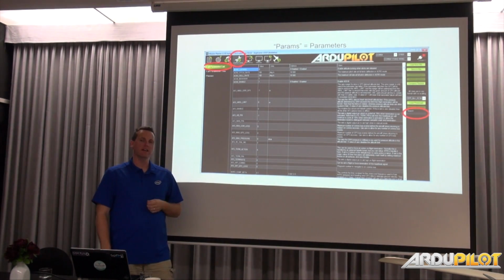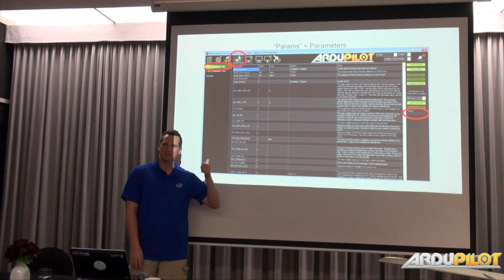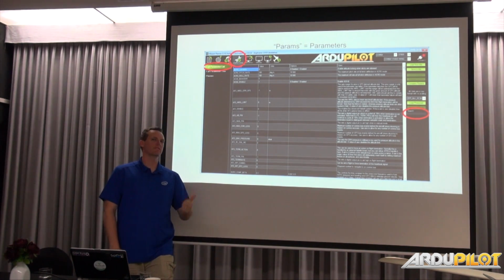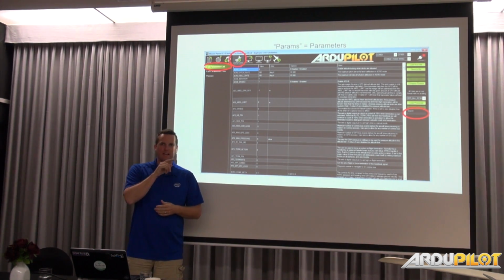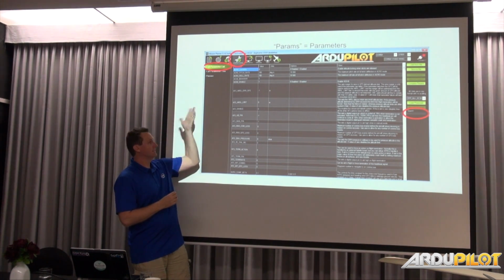I didn't know where to put this slide, but before I talk about the next stuff, I can answer this. There's parameters, lots of them, over 1,000 to play with. And this is where to get to them all. A lot of people go through the wikis and the wizard, and they say, "Oh, it's set up for auto landing," and all they see is the standard parameters. In Mission Planner, you go to Config, then Planner, and then there's advanced options, and the labels change a few times. But anyways, put it into advanced mode, and then the full parameter list comes up, and now you get this giant thing.